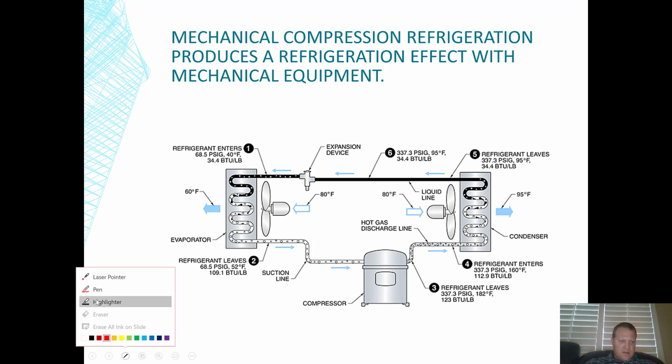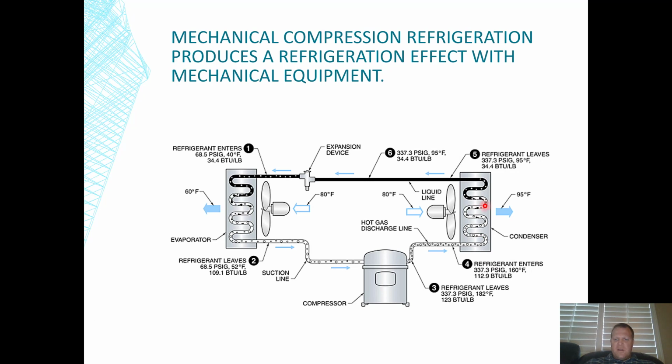Let me turn my laser pointer on. There we go. So the refrigerant is compressed as it starts to go through the coil around the condensing unit. Air's blowing across it, cooling off the pressurized refrigerant, which then turns into a liquid. It goes through a phase change, and in order to go through that whole process, it gives off a lot of heat, right?